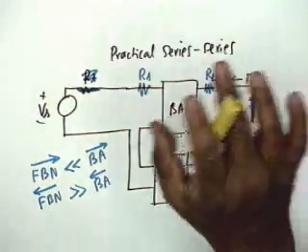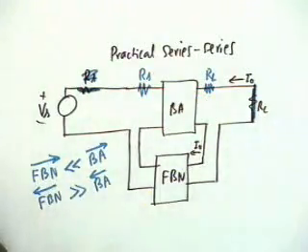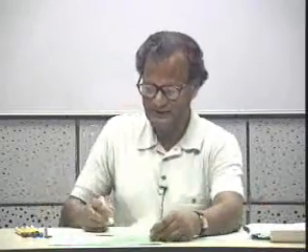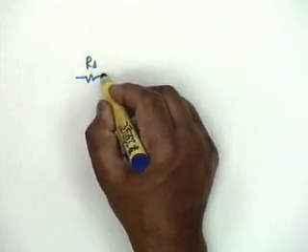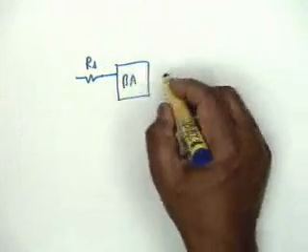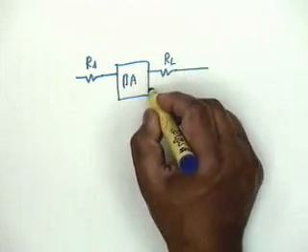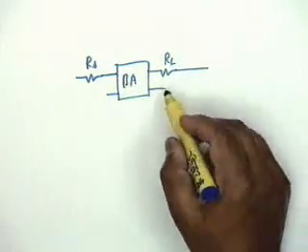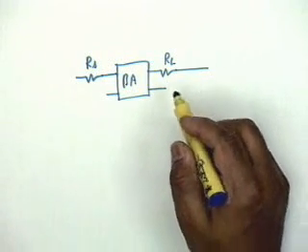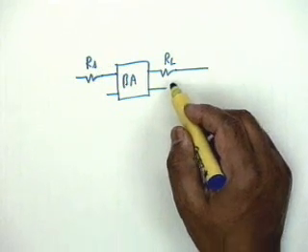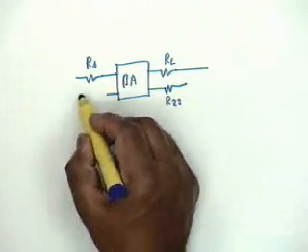Now we have to include the impedances of the feedback network. Without going into any model, let me do this as a bypass route, without going into an appropriate model. We will argue what the model should be later on, but without going into this, you see what I should do, let me draw the A circuit right from this one. The A circuit would be RS, basic amplifier, and then RL. Now obviously what will happen is two resistances will come at the other end. Okay, two resistances, call this R22 and call this R11.